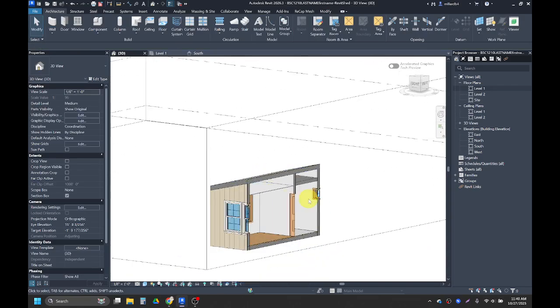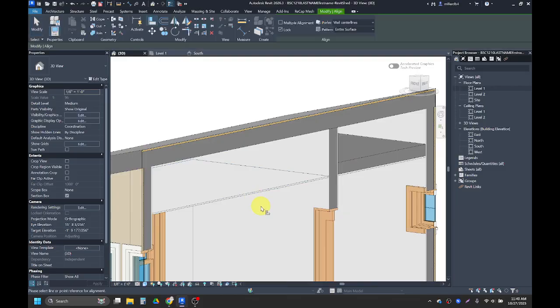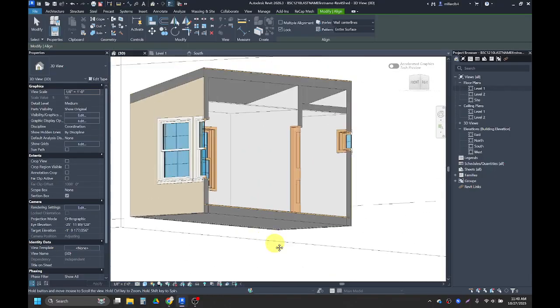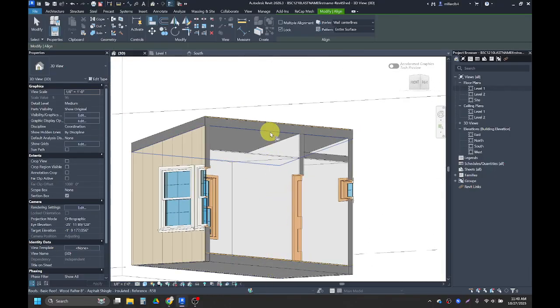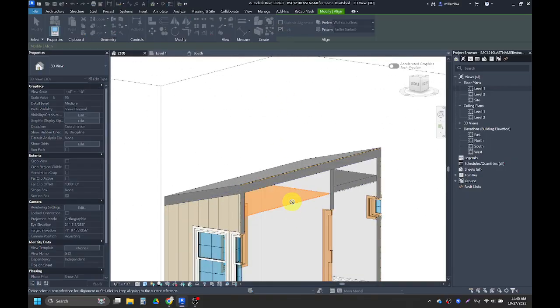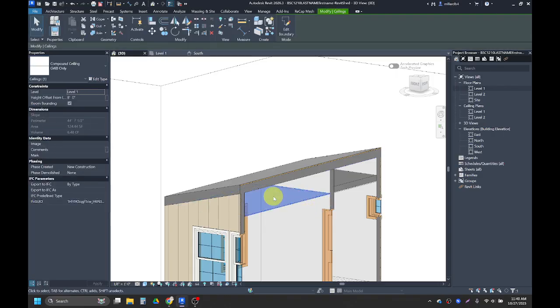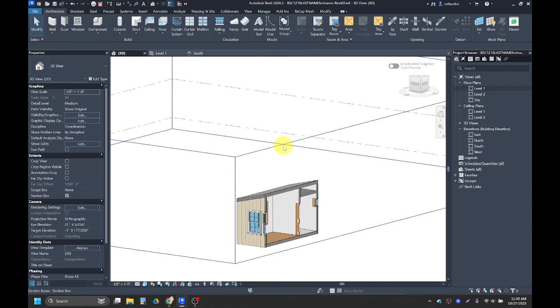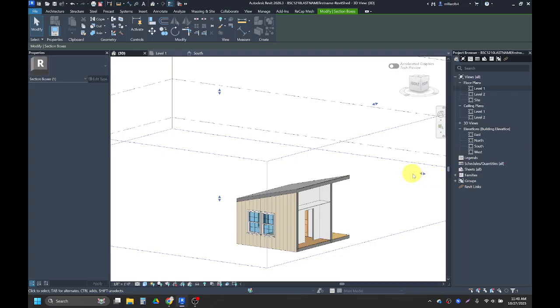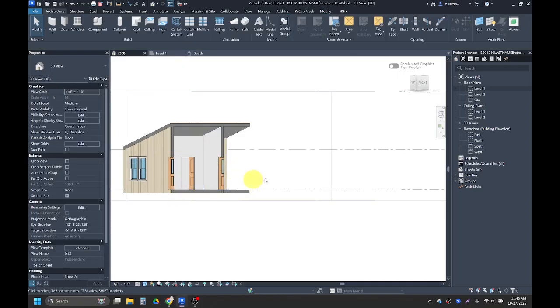So what I'm going to do is use a line to kind of bring it so that it is going to sit flush with there, because this is just gypsum wallboard in there. So I'm going to use keyboard shortcut AL for the align tool. I'm going to orbit around in this section cut view so I can click on this part of the roof, and then I'll orbit around so I can click on this face of it. And it says can't change the plane of the ceiling sketch, so bummer. So it looks like I can't do it that way. So let me just delete this ceiling. Let me pull my section so I can look in the other room. Click on this ceiling and delete it.